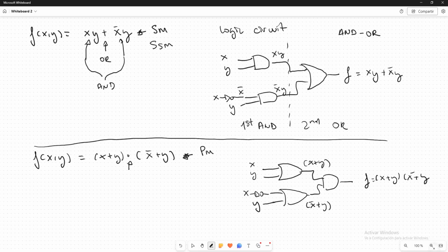And you can see that here the first level is OR and the second level is AND. So if you find a circuit that is asking for an implementation in two levels of OR and AND gates, indirectly they are telling you that you have to look for the minimal product. Okay? I think this is quite easy to understand. Just note that adding inverters doesn't increase the number of levels, okay? Inverters don't count as logic gates when we count levels, only the other gates, OR, NAND, etc.